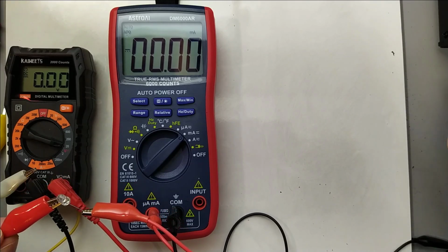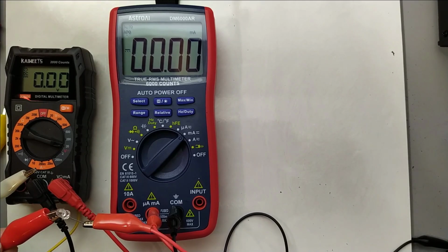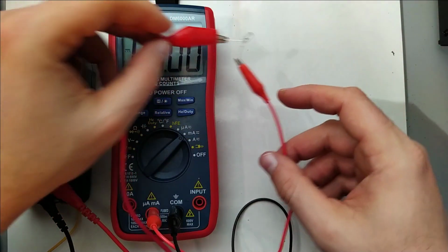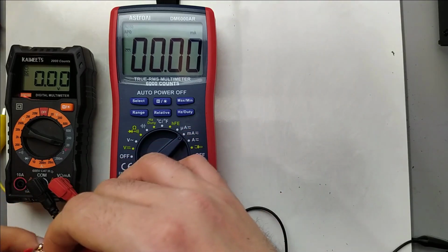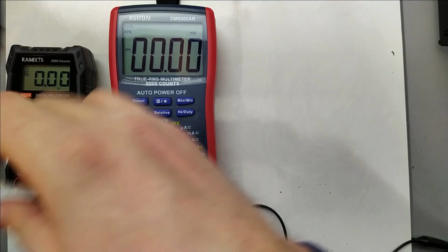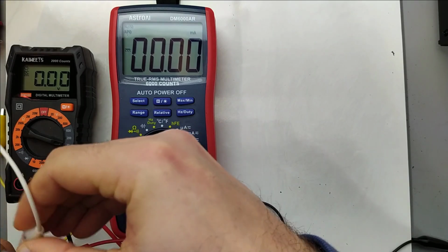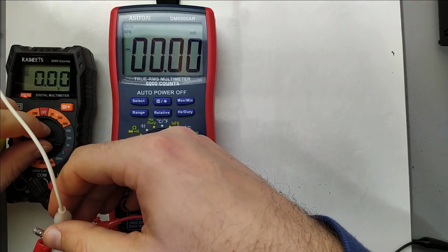In this case, I would like to start our experiment from reverse polarity, and then we will go to forward. So now let us connect in parallel a voltmeter, because we also need to monitor the voltage drop over this LED.